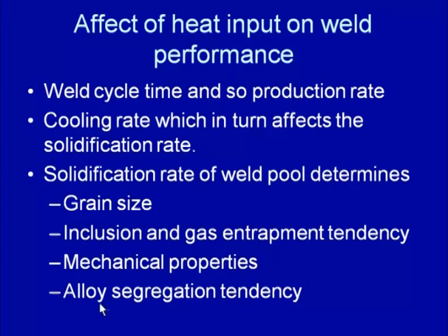So, the heat generation in the weld pool affects, one, the weld cycle time, and so the production rate, and the weld heat generation also affects the cooling rate which is experienced by the weld pool and the heat affected zone during the welding, and the effect of the cooling rate in the weld pool directly affects the solidification rate, and which in turn affects the grain size.